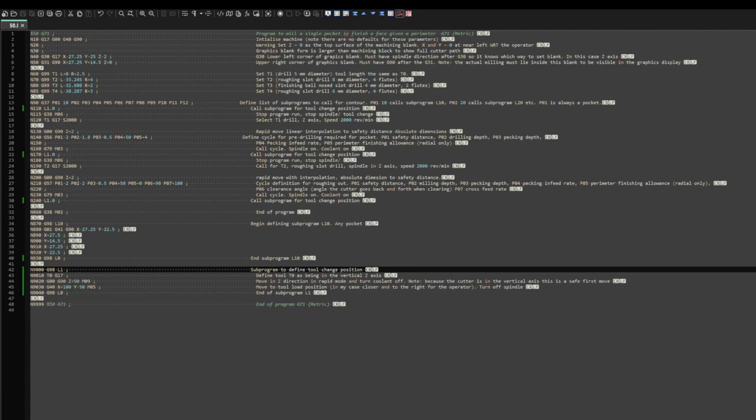Here is a program that I've created in G-code, and I'm going to use it as a demonstration of how you can make G-coding easier. The program itself is a single pocket, but in fact I'm using it to create a datum face on a small part that might have a problem with a big fly cutter.